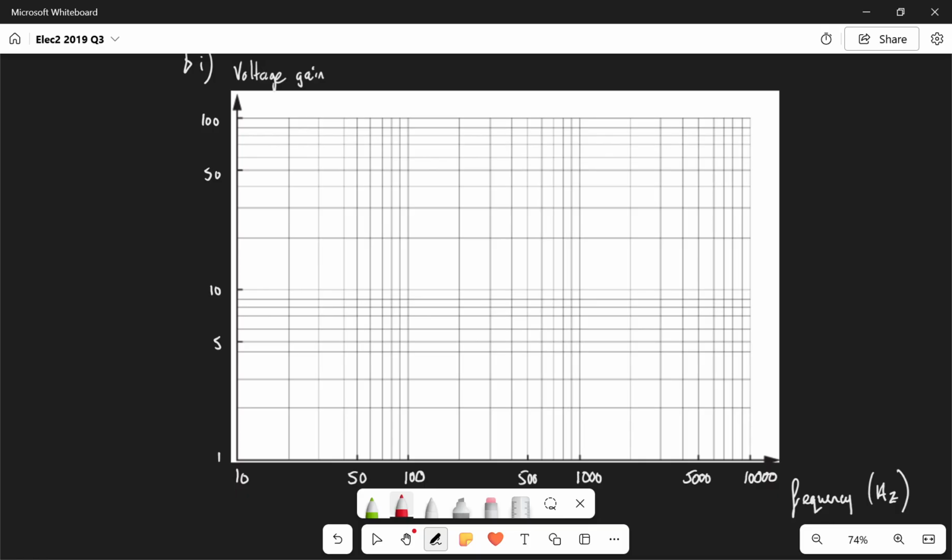Now this means we're looking at a bass boost active filter, and bass boost active filters mean that we're looking for a particular graph shape. Now, we know that 200 is a key frequency, so if we look along the x-axis, we need to recognize where 200 is on this logarithmic scale, and that is here.